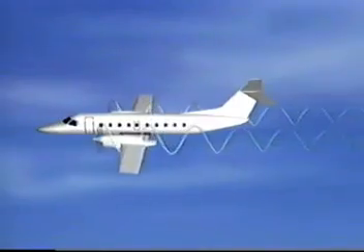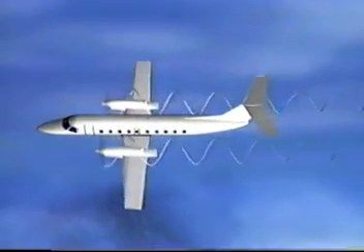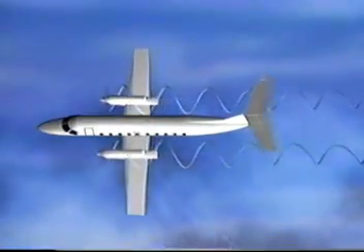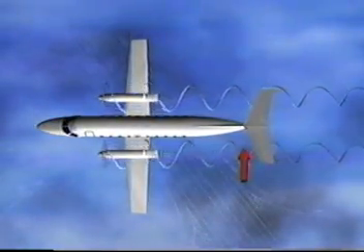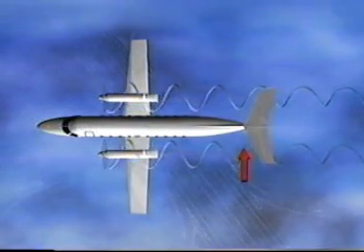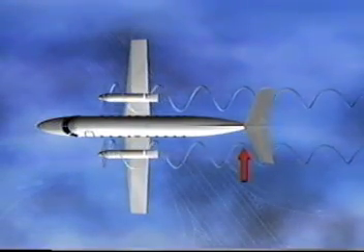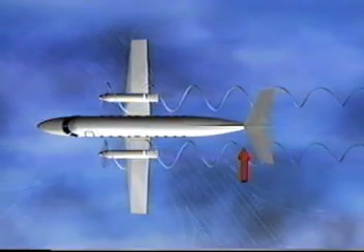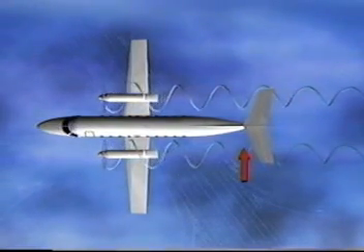Well, due to the direction of rotation of the propellers to the right, clockwise when viewed from the rear, and this configuration is adopted by most manufacturers, the spiraling slipstream strikes the fin on the left, causing a left turning moment about the aircraft vertical axis. This effect is perceptible at high propeller speeds and low forward speeds, and varies from aircraft to aircraft.